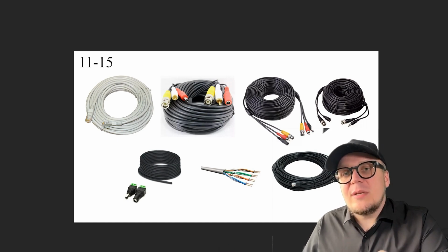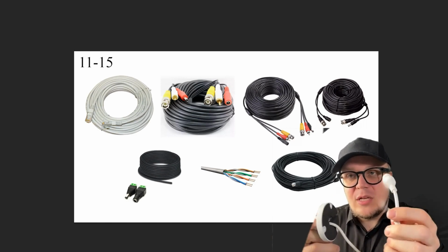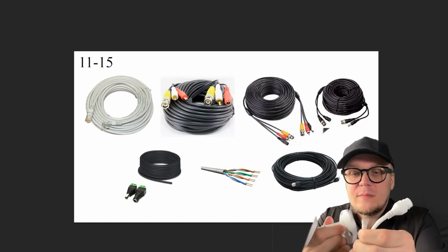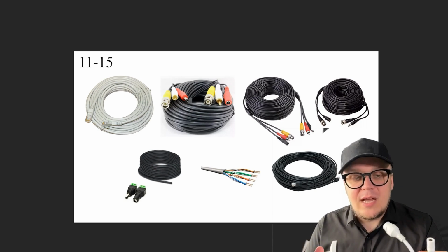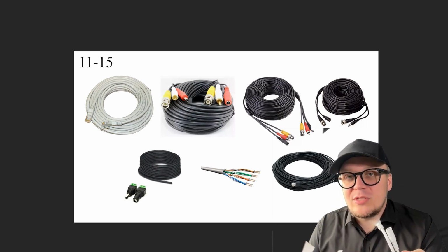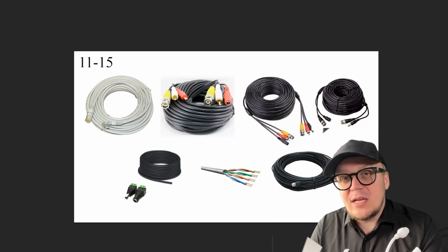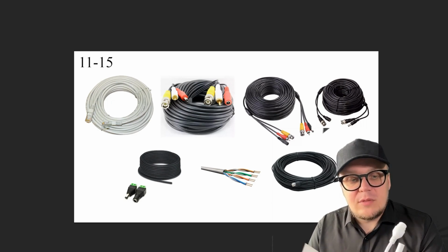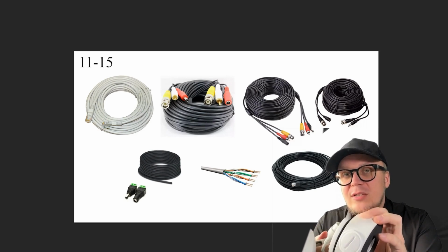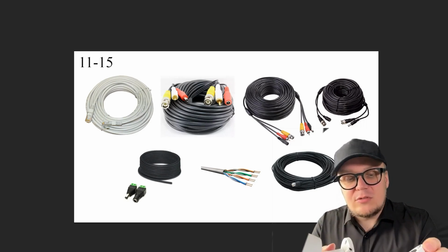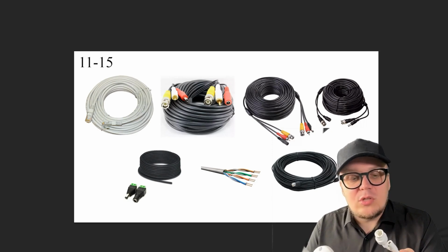And another common mistake is when people want to embed this little wire, this part of the camera, into the wall. And this is a mistake, because you should be able to remove the surveillance camera at any time. That is, a warranty case might occur, or the camera might simply reach the end of its lifespan and you need to replace it. You mount the camera through the base. That is, the connection point with the connector is located near the camera itself. You spend 5 minutes and replace the surveillance camera with a new one accordingly.